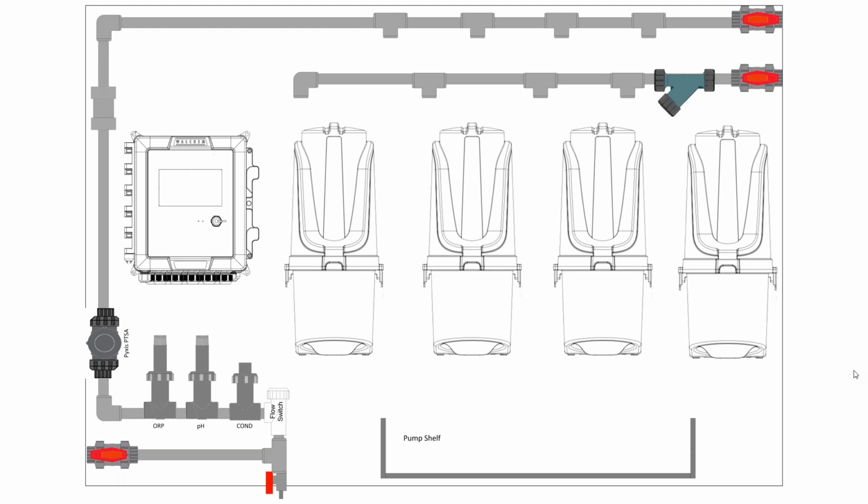Regardless of which one you do, you are sending a UV beam through a quartz glass that is going to get covered over with gunk and slime and little bits of things, and you are going to regularly clean it, or you're going to inject chemistry at the wrong levels. The default is when you see less PTSA, you want to bring more PTSA in. If you blind off the sensor, that's a lot less PTSA as far as the sensor thinks, so you're going to overfeed your chemistry because you're not cleaning the glass. So it is a regular maintenance item. It is part of the program, and it's something you should probably do every month.